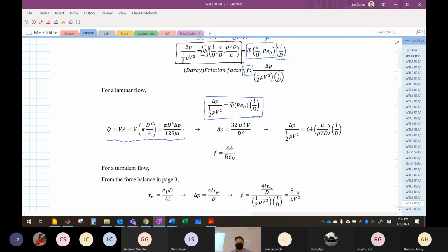Then we just rearrange the terms here in terms of viscosity, length of the pipe, velocity, and diameter for the pressure drop. All right, that's what you can do. Still the same equation. Then just divide by the dynamic pressure, 1/2 rho v squared. All right, we can do that. Then what you can see is you can group some of the constants and the variables in terms of the Reynolds number, the reciprocal of the Reynolds number, and the pipe length over diameter.